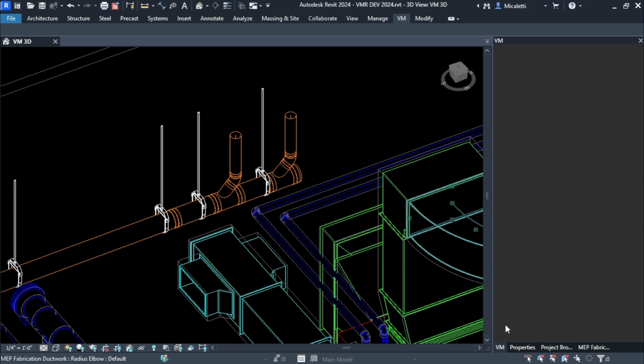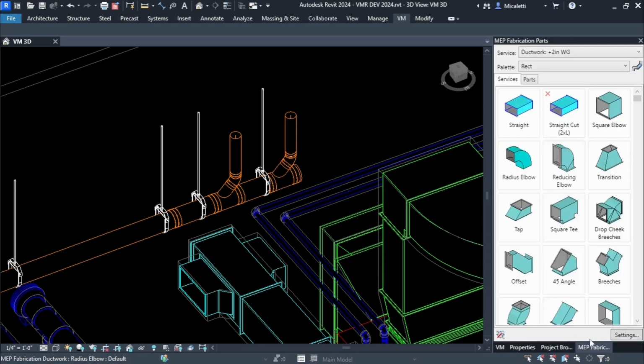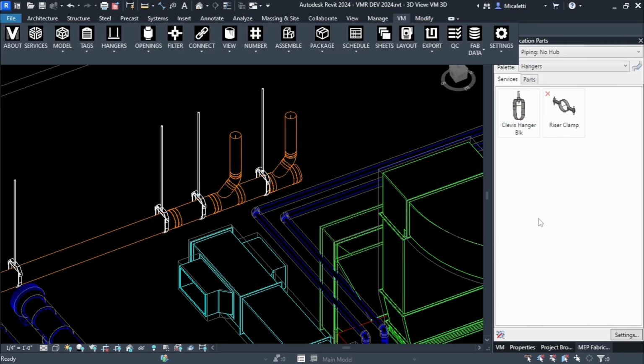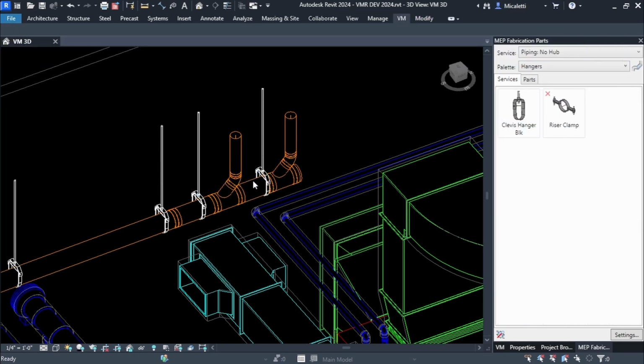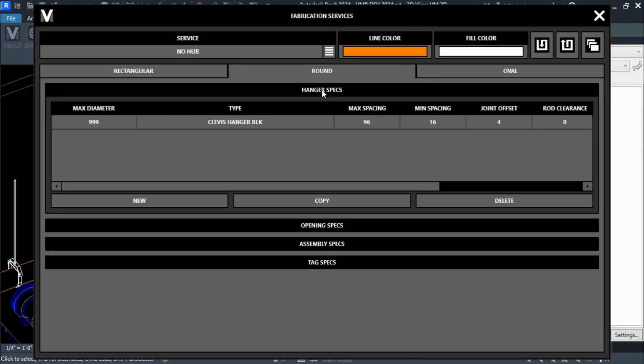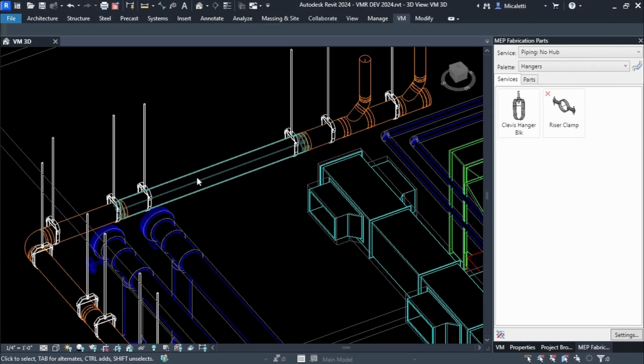Now in this way, I didn't have to go pick the hanger, right? Show service, go to hangers, and then I have all these hangers to select from, and I'm not sure at this size pipe with this size insulation, what the hell hanger am I using? We're not leaving that up to the designer. That's all built right. You're still getting the hanger in the service that was spec, right? But you can place them manually now wherever it's missing one.